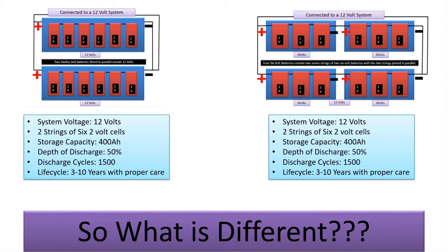If you are choosing to pay a bit more for the AGM batteries, you're paying for storage capacity, ease of maintenance, the ability to store batteries inside your RV without extreme venting, and most importantly, in my opinion, the faster charge rate. Because the faster charge rate allows your solar system to put energy into the batteries more quickly and to utilize your generator, these are the right batteries for me.